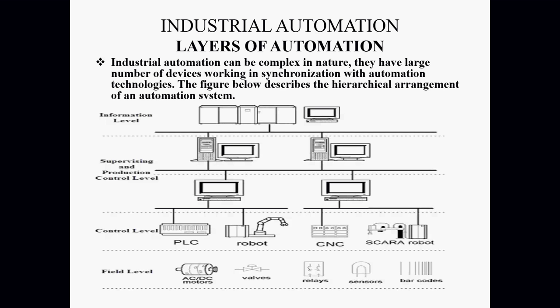From there, through your signal cables, you're going to receive or send out information to these field instruments. And this information is being received and sent out by the controller, which evaluates the inputs that it receives, and based on that takes a decision after following the logic that it has in its memory.